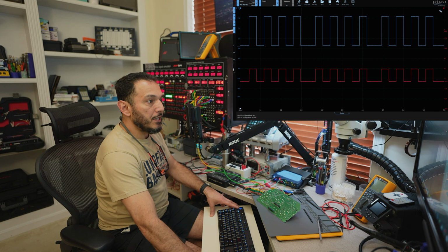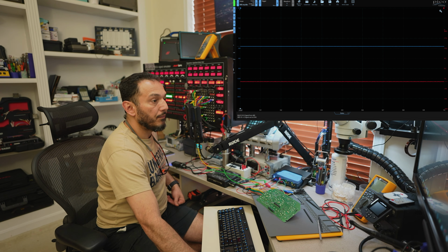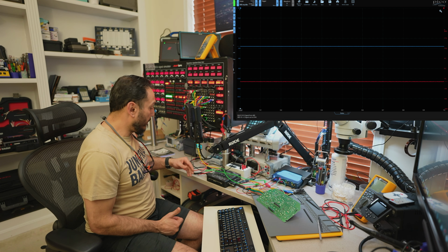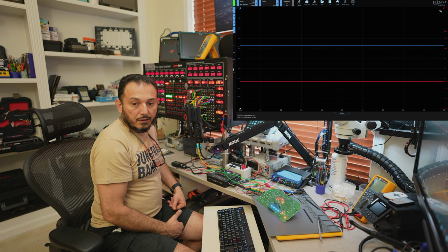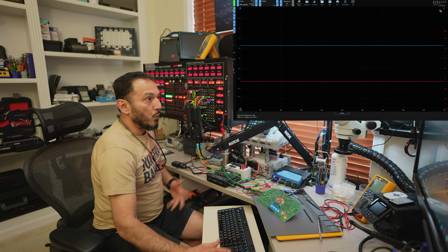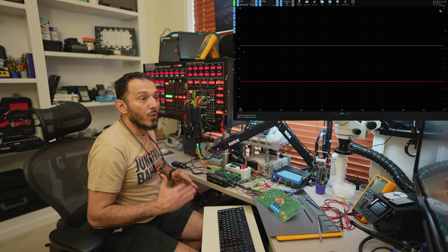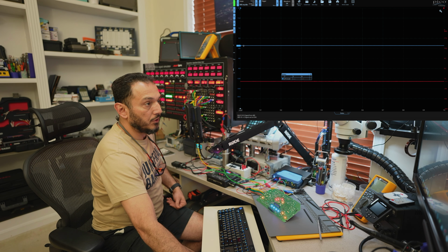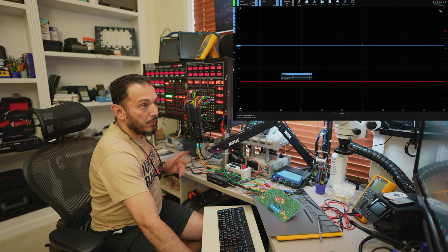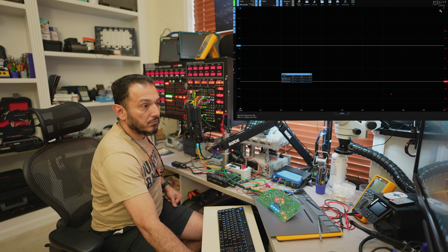All right, so let me go over to Pico. Let me run Pico first because you're going to see those signals disappearing now because nothing is on. I'm going to first power on the instrument cluster. You're going to see the lights and a ding. That's the instrument cluster coming on. With just the instrument cluster on, both signals are reading from 0 to 20 volts, which is very important. The blue signal, remember, is my signal being provided, so I should not be reading anything. And the other channel is also at 0 because nothing is going out.